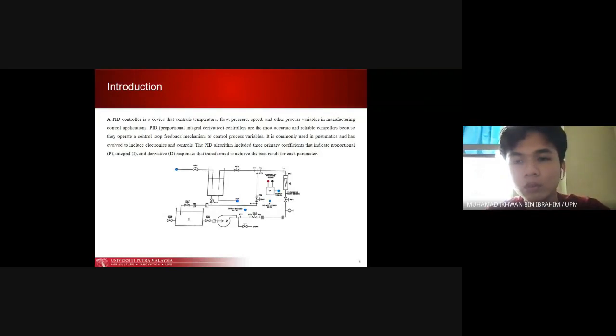The performance of a controller system is typically assessed by using a step function as the setpoint command variable and observing the process variable response. Typically the response is assessed by analyzing specific waveform features. A loop cycle is also an essential parameter of a closed loop system. The interval of time between calls to a control algorithm is referred to as the loop cycle time.